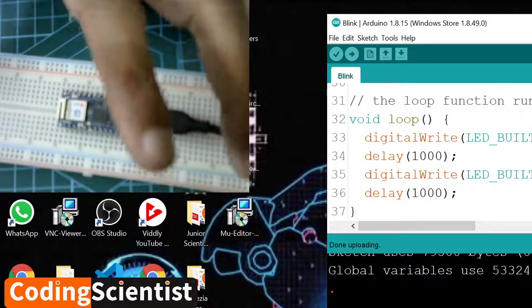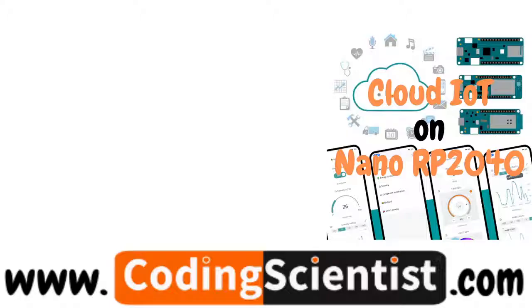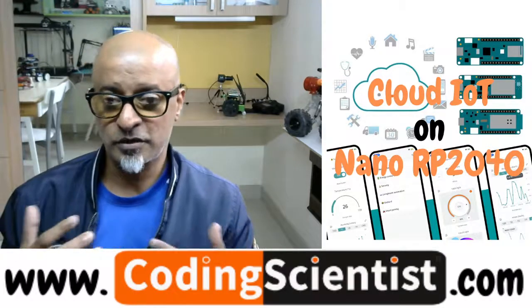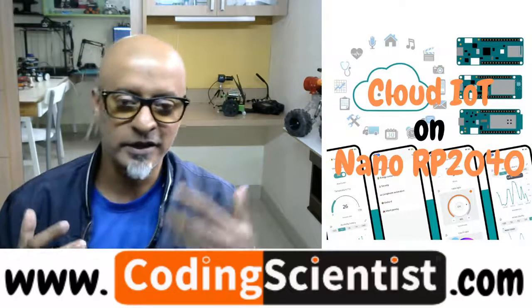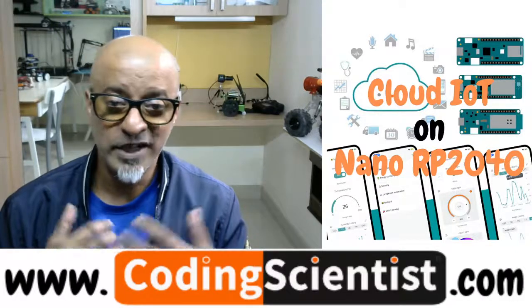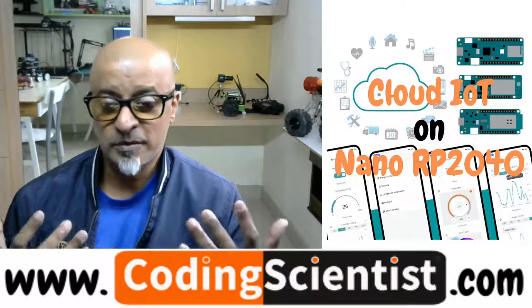Guys, it looks like there is some issue with the firmware itself. You saw me troubleshooting. I'm trying to debug one by one, either this IDE, that IDE, this setting or that setting. But it looks like the firmware within your RP2040 board itself is not working. The MicroPython firmware is not getting detected for some reason.